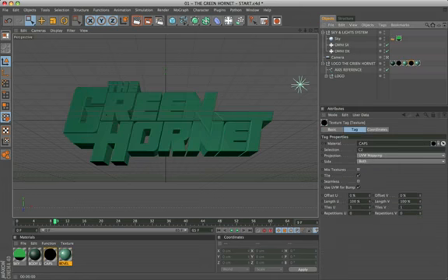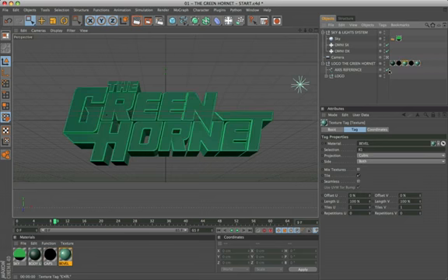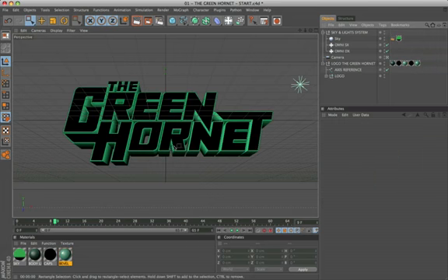The cap end is the same as the cap start, but with selection C2. Most importantly, for the bevel material, you must activate on selection R1 and R2. OK, view the result.